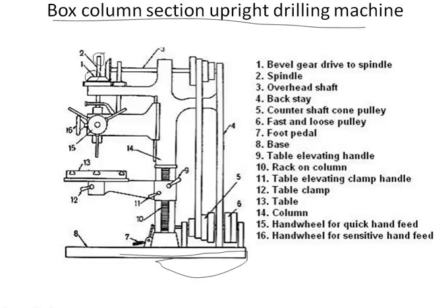First of all, we'll discuss the parts. That is the base. It is the part of the machine on which the vertical column is mounted. The top of the base is accurately machined and has T slots on it so that large workpieces and work holding devices may be set up and bolted to it.